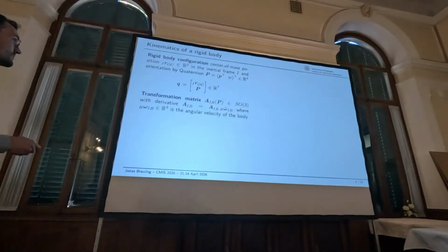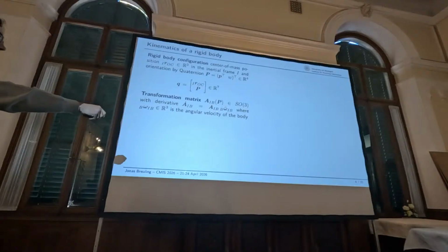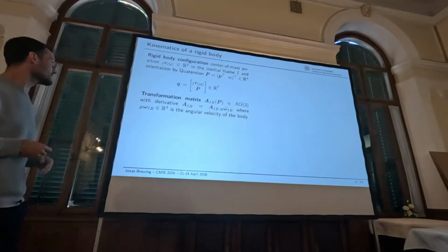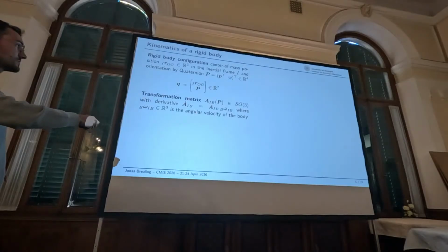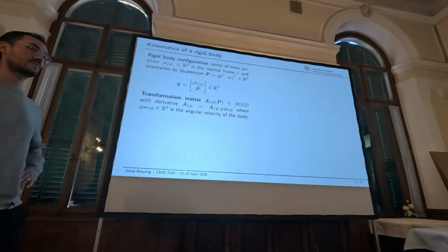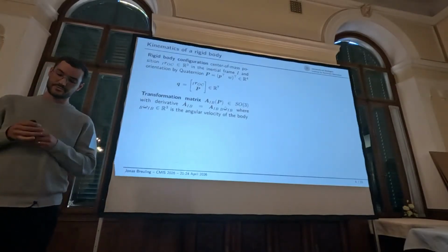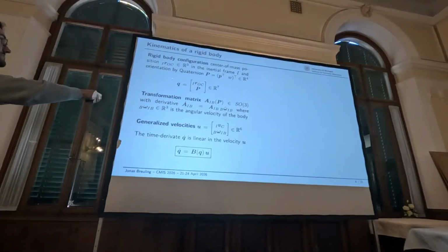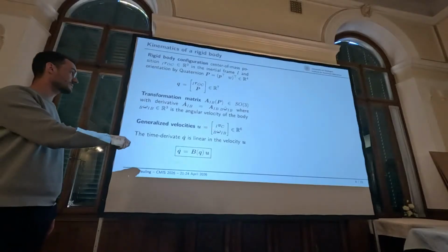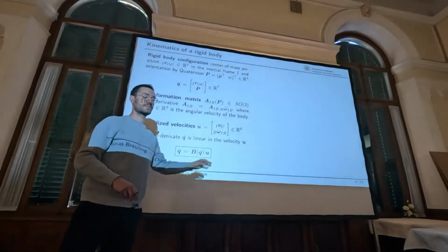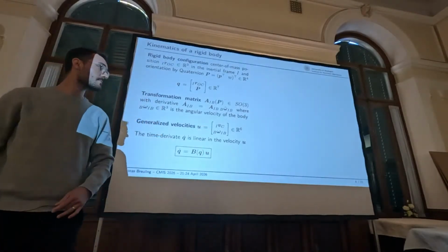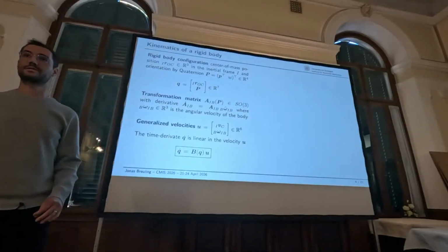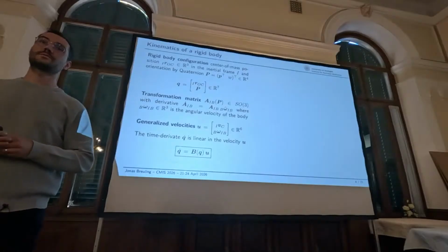With that, we can compute elements of a rotation group and their time derivative. It turns out that it's related to the angular velocity of the body. A very clever trick is to use, in contrast to the time derivative of the generalized coordinates, new generalized velocities: the velocity of the center of mass and the angular velocity. This allows us to relate the time derivative with the generalized velocities, and we get a very nice simple dynamics from that.